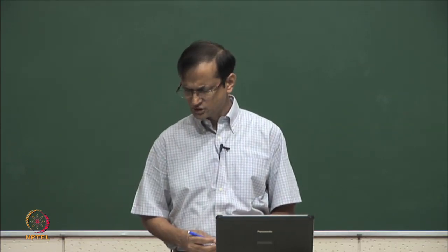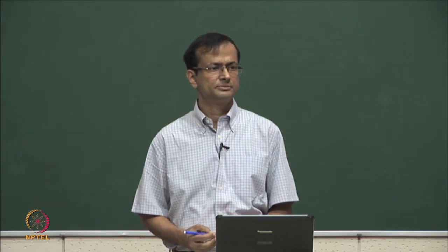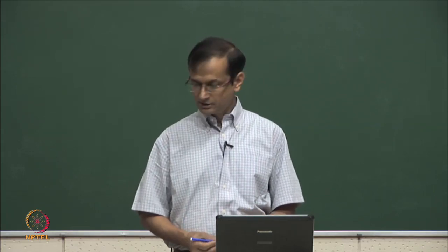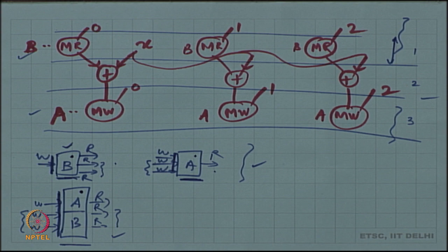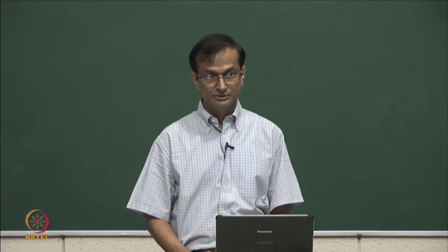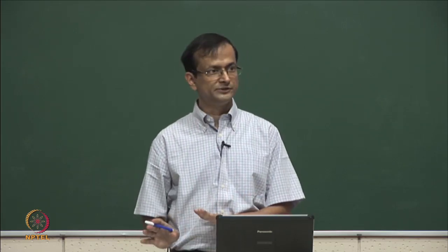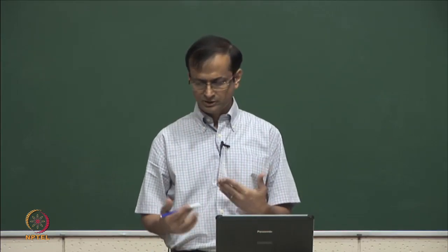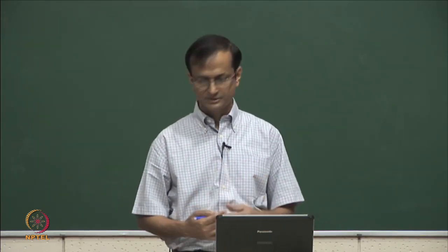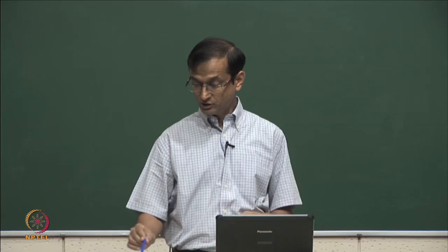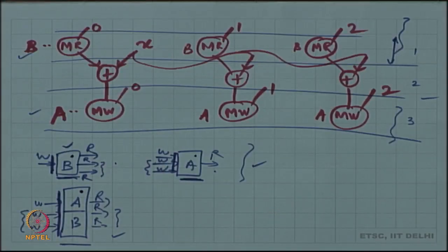But what if I had constrained you in terms of the memory ports? Say I do not give you a 3-port or a 6-port or a 12-port memory. Instead of the loop iterating from 0 to 3, what if it was iterating from 0 to 100? I could still do the unrolling of the DFG in a way that is correct, but after that, what is the synthesis related argument? If you want a similar performance, then you need a 100-port memory. Not just that, but the access time should also fit into the same clock cycle, which might not happen.